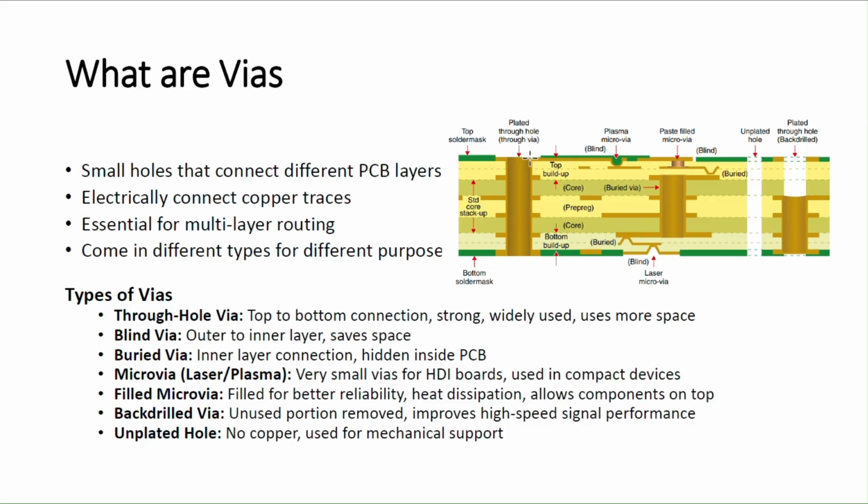For example, if this is a 5 volt net and this is a 0 volt net, then it will not connect between these two layers, because there is a clearance defined. We will be defining some clearance in the tool, so because of that clearance it will not automatically connect to the internal layer, because it is of a different net.